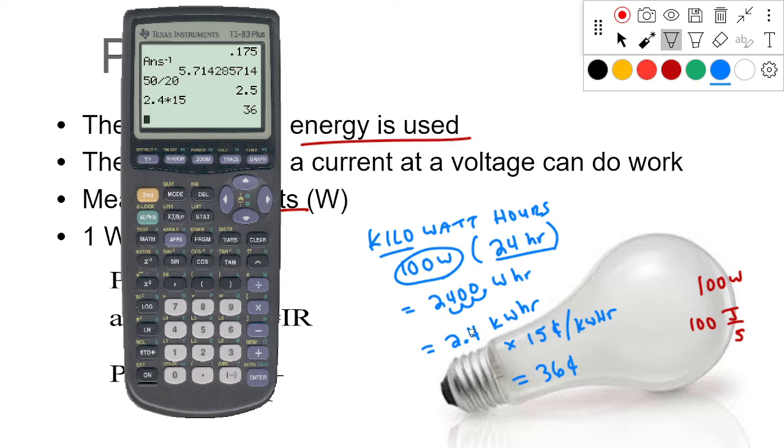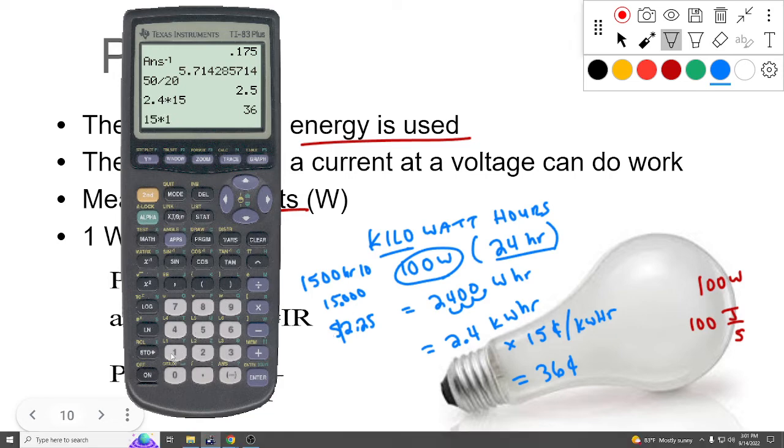A hair dryer is about 1,500 watts. Your stove is about 1,500. You leave that on for 10 hours, now we're talking 15,000 watt hours, 15 kilowatt hours, and now you're about $2.25 that you're talking about. So don't go leaving this stuff on. I think I did that right. 15 times 15 cents would be 225. Move the decimal place. Yeah, $2.25 to leave your hairdryer running for 10 hours or something.